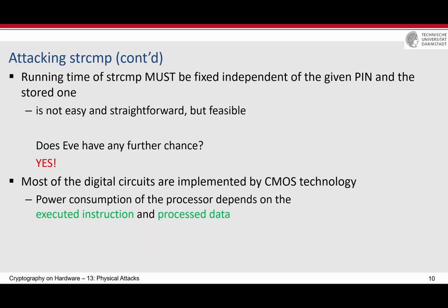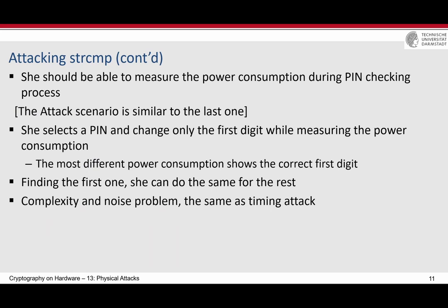So there is a dependency between the power consumption of a device and the executed operation. At the same time, if the operations are the same, for example two AND instructions, but the operands are different, the power consumption again depends on the operand. And you can use this information to understand what is going on.